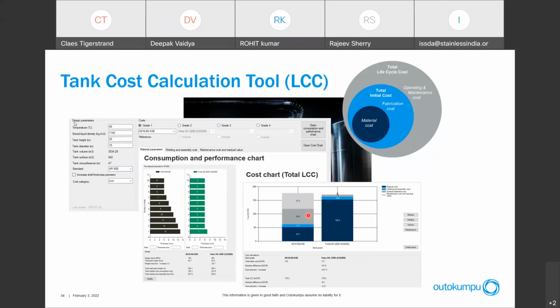However, you have to spend a lot of cost on the rubber coating, and if you need to recoat the carbon steel once during the service life, that adds a lot of cost. So for the total cost, actually the carbon steel tank could be more costly than the stainless steel, even though it's much more expensive from the beginning if we're just looking at the cost per kilo.